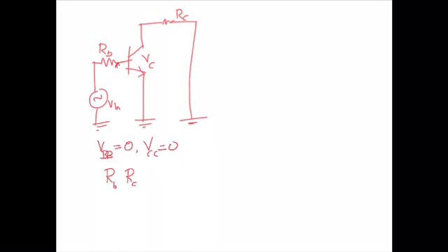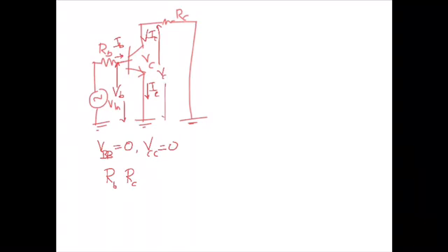Similarly, capital R with a small c represents the collector resistance. I can write the base voltage as capital V with the suffix B, and the current flowing into the base terminal as capital I with a small b, that is the AC base current. Similarly, capital I with small c is the AC collector current, capital I with a small e is the AC emitter current, and the total output across the collector terminal we call capital V with the suffix C. This is the collector voltage.